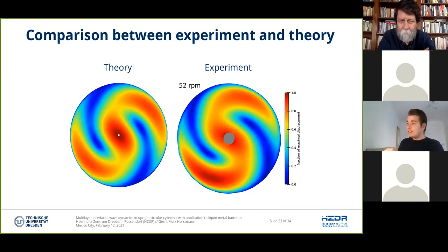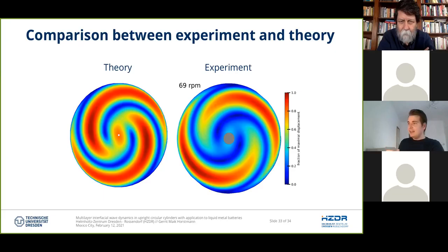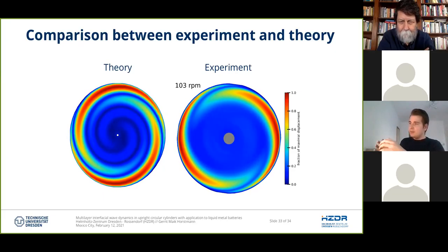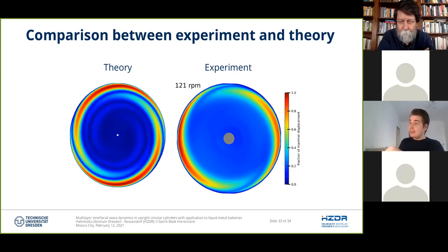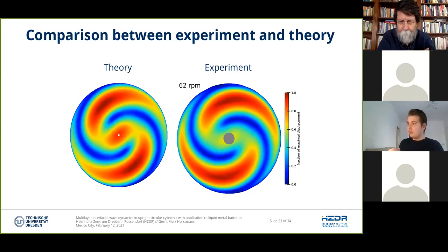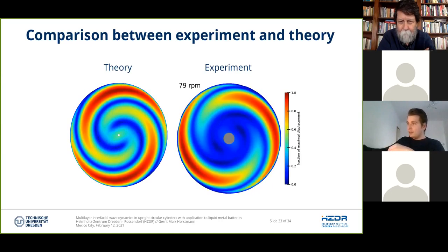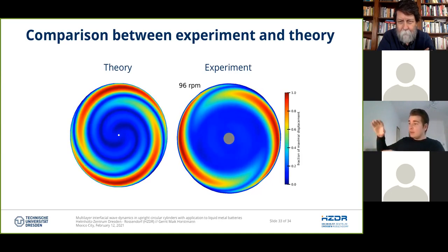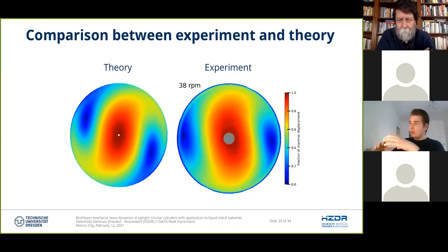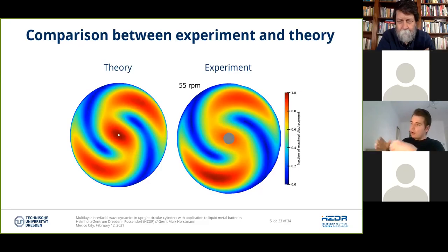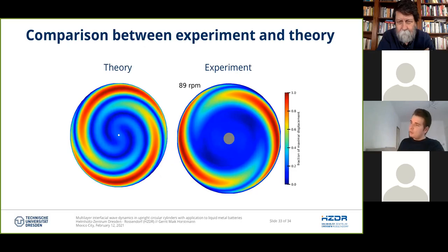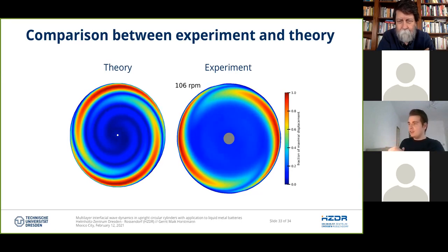The second reason is that damping is far higher in two-layer systems. To my best knowledge, we have made the first interface sloshing experiment, at least under orbital excitation. So all the wave crests here are very small, on the order of millimeters. So very stable linear waves, which are not possible to excite in water or in less viscous one-layer systems.